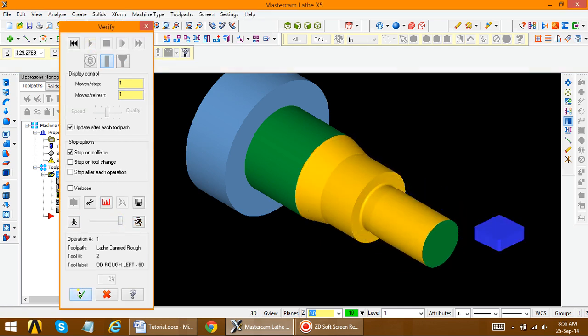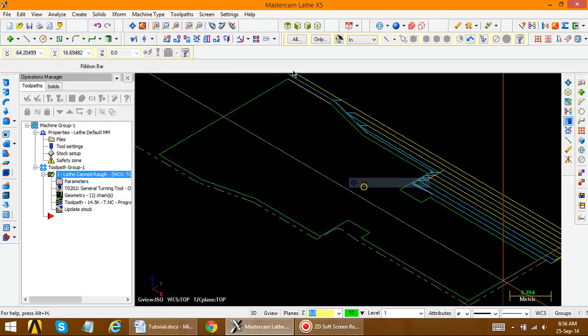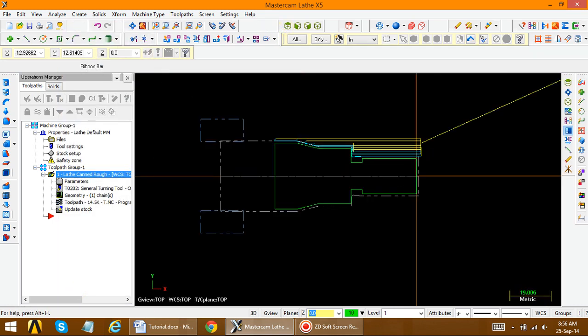So this is performed. Now next, fit top view. Now these yellow lines, green lines are shown. That is the tool path, cutting tool path. So to hide this, just press Alt T, and again to visualize this, press Alt T. It's simple. So I hide this, Alt T.